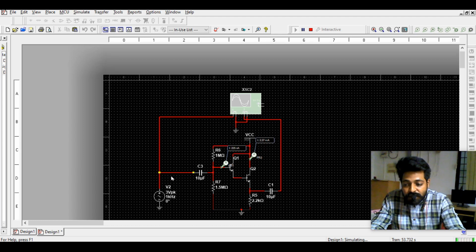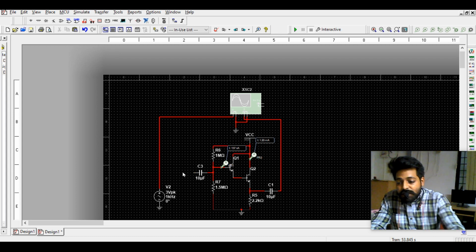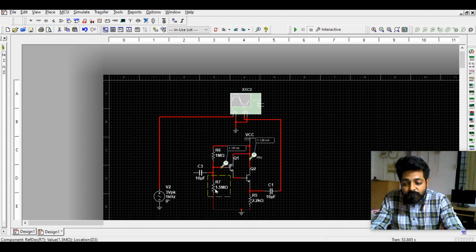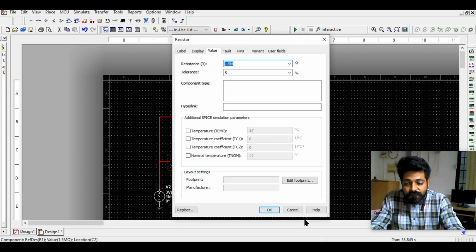With the arrangement of two transistors connected over here, with the Darlington connection, I have to increase the resistance. I have to observe that increased resistance across that. For that sake, I will be using the maximum power transfer theorem, where source impedance equals load impedance, which we have already used in the previous sessions to calculate the input resistance. The same method, let me follow. So I will be using a test resistance here.